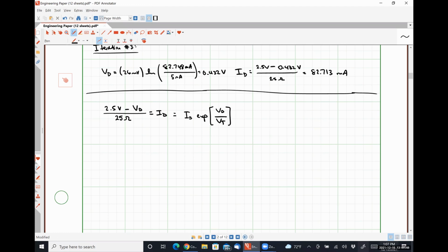So now, if I say that this part is equal to this part, and I put it in the numerical solver of my calculator, it will be able to solve for what VD satisfies both sides of that equation simultaneously. Your calculator is doing the iterative process that we are doing. It just does it way faster, but it's literally doing the exact same thing. But we have to give it in a one-equation setup that's constrained to some constant value, which is what would happen if we moved stuff to the other side of the equation.